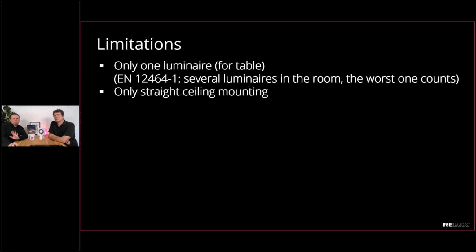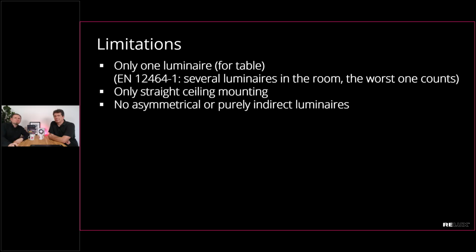Most of the situations are like this, but if you have another situation, it's not applicable. You can potentially get values out of the software, but it's not applicable according to the standard. The same goes for asymmetrical luminaires. So if you have asymmetrical or double asymmetrical luminaires, it's not applicable.